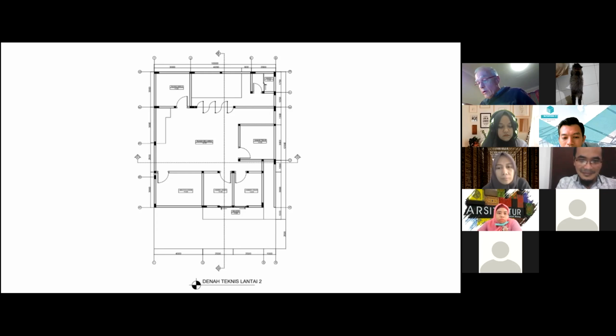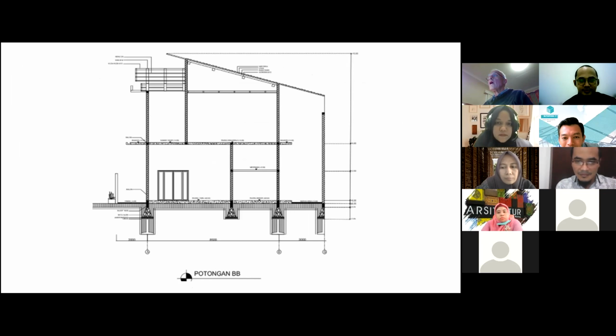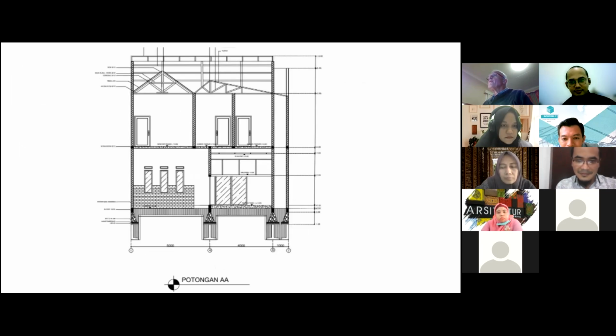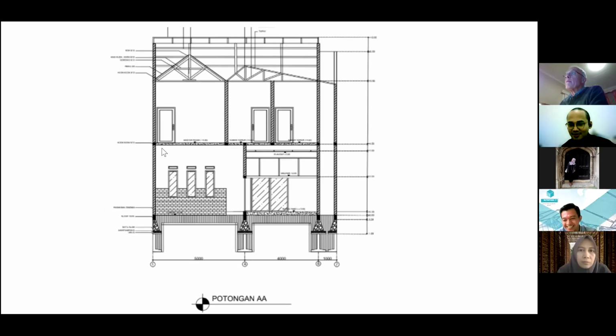Now, if we look at the beam layout, sorry, we haven't got a beam layout. Oh, I haven't got one here. But essentially, the student hasn't shown the beams required to support the edges of some slabs where there are penetrations. And so the student needs to show beams under walls, and also show the elevation of beams under the slab.